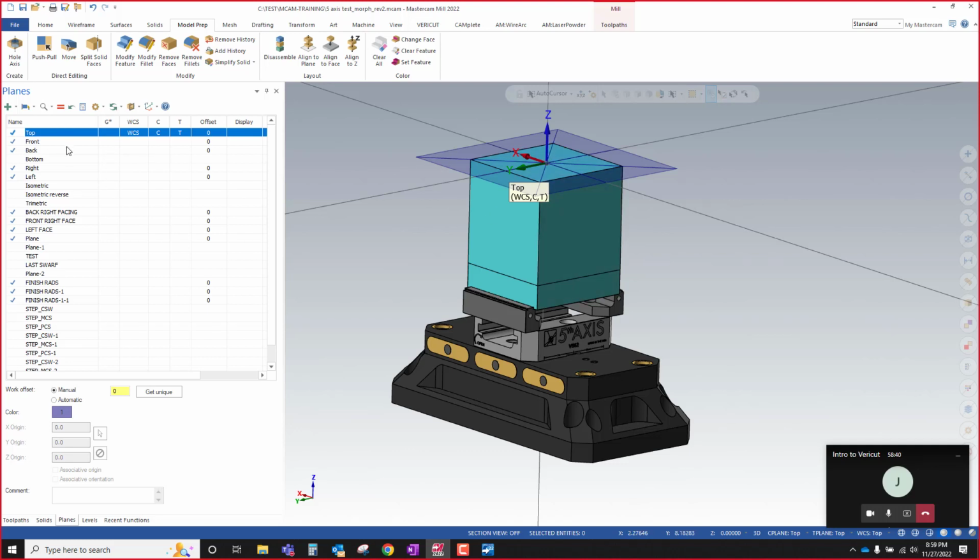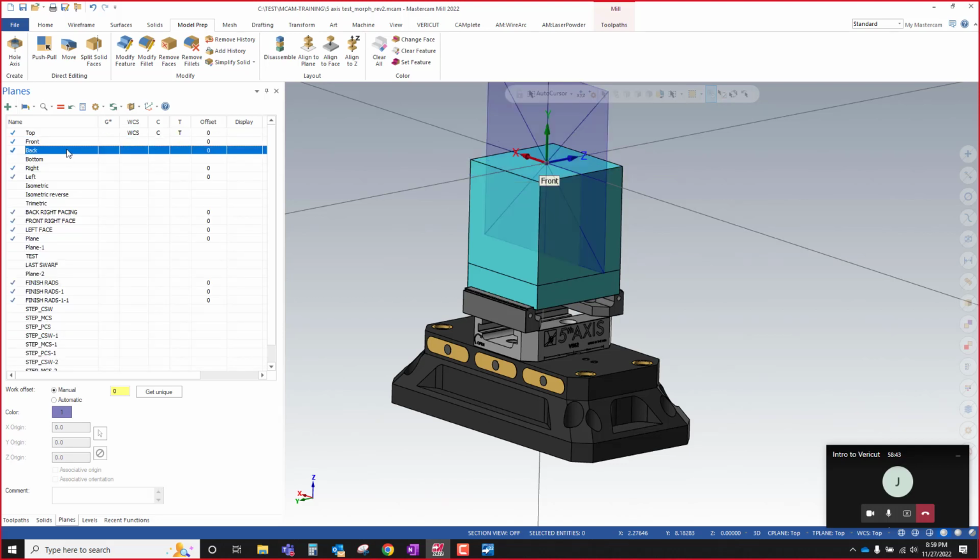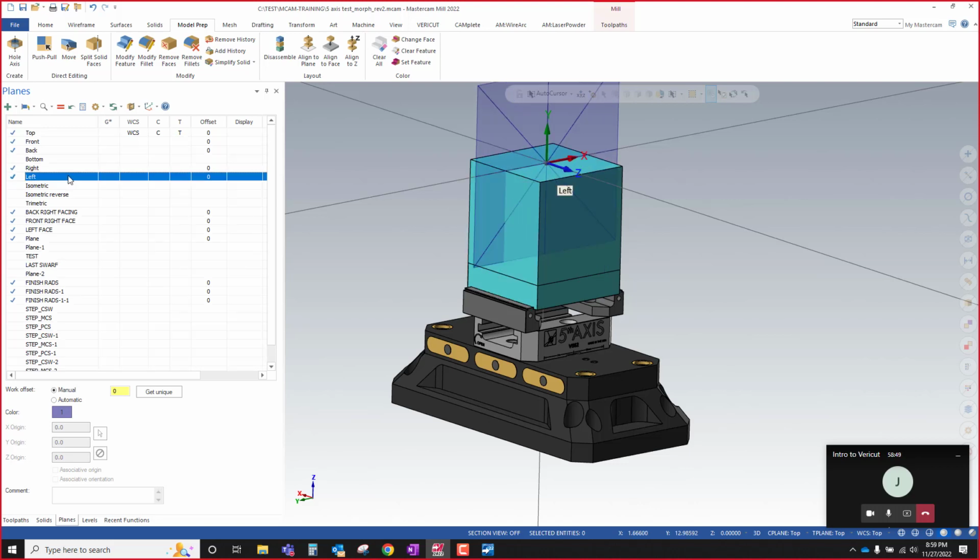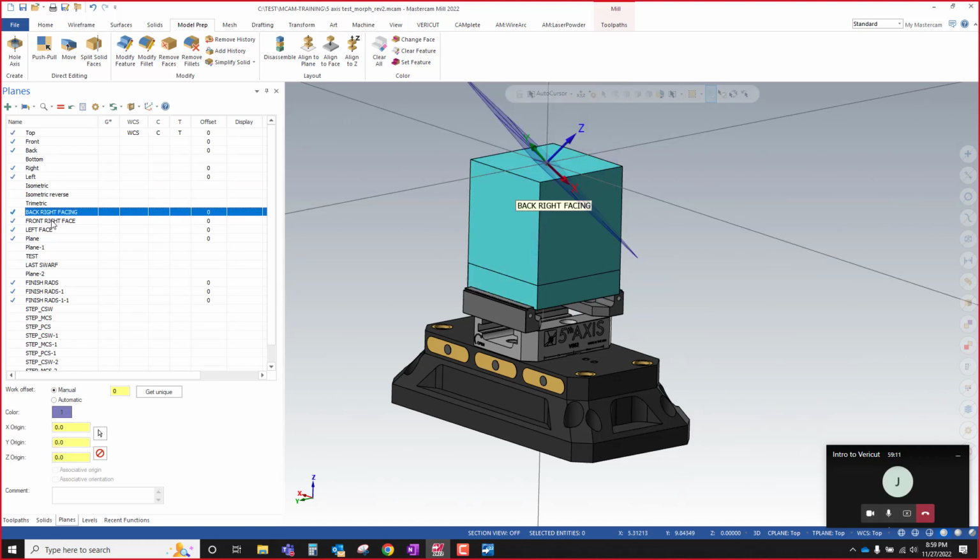That being the case, I need to make sure that any plane that I use has the same origin. Because with those dynamic codes, that origin point, even though the plane orientation changes, the location should not. Unless you're going to physically set another work offset on the machine, which you could do. You just want to be sure you're setting the work offset at the top. So with the machine at BC0 for UMC 750.